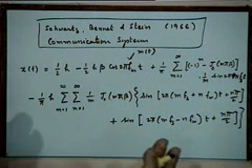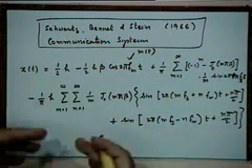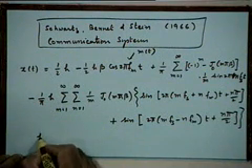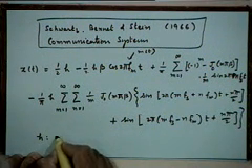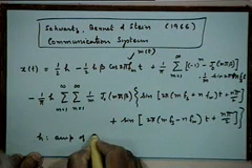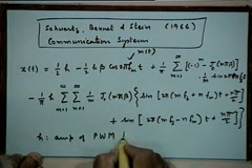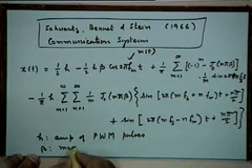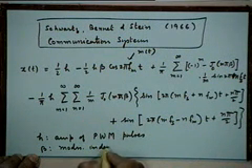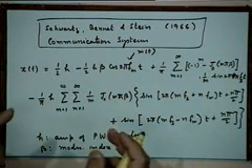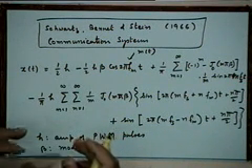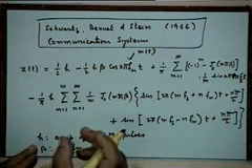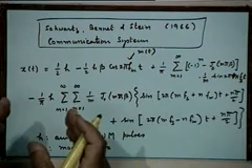Let's see some pattern in this madness, if there is anything. H here refers to the amplitude of the PWM pulses. Right? And beta is a kind of modulation index, which I will not define formally, but basically it's like this: beta would be equal to 1 if you use the maximum possible pulse width that you can have.